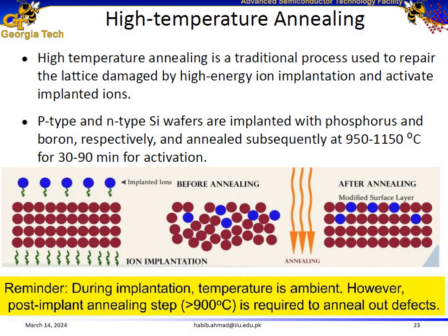Annealing is actually a high temperature technique which is performed for a particular amount of time. For example, consider the crystal lattice once again. Assume this is the periodic arrangement of silicon atoms inside the wafer. We introduce high energy implanted ions into this crystal lattice. These ions dislodge the silicon atoms close to the surface from their lattice sites. So now this layer over here, which is close to the top surface, becomes amorphous.